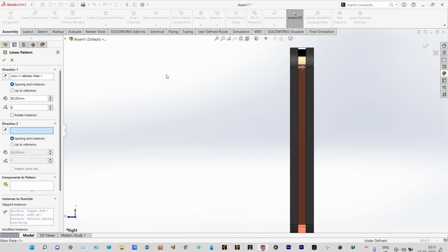It will go in the forward direction, so we can change the direction from here itself, right? Okay, fine. Initially, 15 main plates you want to move in the forward direction. The thickness between these plates is 20 millimeter, so from here to here it will be 40 millimeter. So we have to move this main plate 40 millimeter away. We want to make 15 main plates in the forward direction. Let us make the number 15 and the distance 40 millimeter.